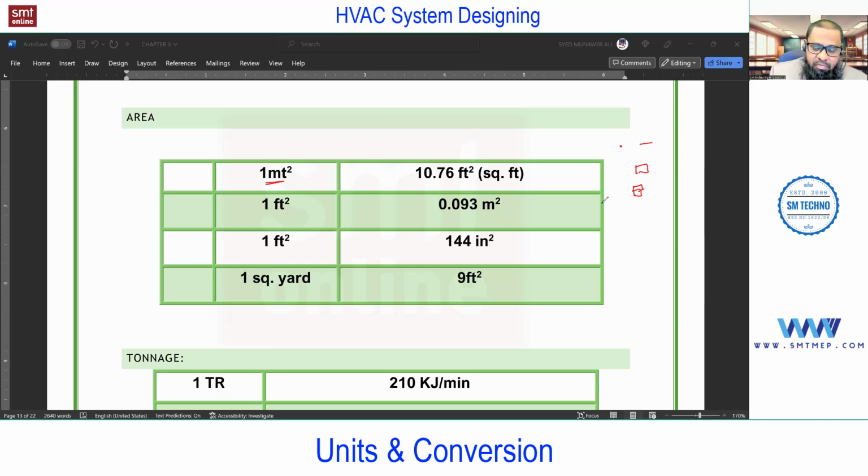In the mind science, you'll find some different dimensions, and in the BIM concept, building information modeling, you'll find up to 7D in the standard, but recently 3 more dimensions were added: 8, 9, 10. In that BIM concept, 4D means 3D plus project scheduling, nothing but time, and similarly 5D is 3D plus project estimation. They consider these as different dimensions, but they are not actual dimensions. That terminology you will use in the BIM concept, but in physics, we have 3D.